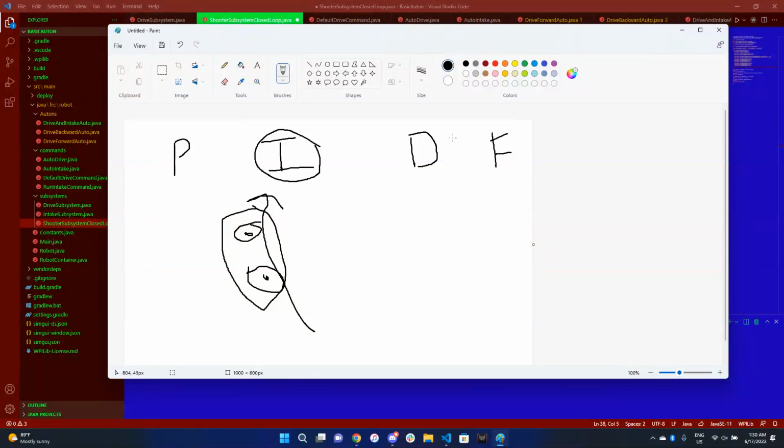Depends. Now our D term is our derivative term, or another way you can view it is a dampening term. Sometimes if your P is still too much, you might consider adding a D term, or a dampening term, to reduce the effect that the P has within your loop. And then you have a feed forward. The feed forward really does most of the work here. And it implies feeding. I like to think of it as feeding RPM into the motor. It's commanding it to move. And the more feed forward you have, the more your robot will actually overshoot.